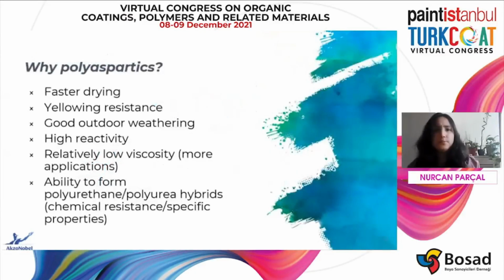Then, why polyaspartics? Polyaspartic ester-based polyurea top coats have longer pot life and they are non-yellowing. They have several application areas due to their relatively low viscosity and high reactivity. In addition, the ability to form polyurethane-polyurea hybrids provides high chemical resistance and flexibility to obtain specific properties.